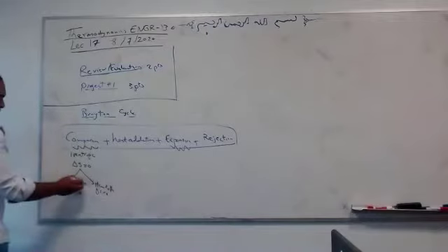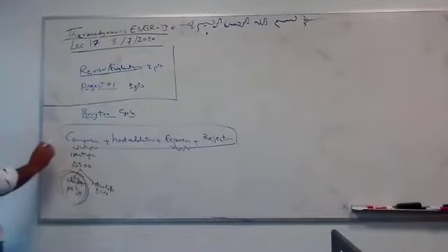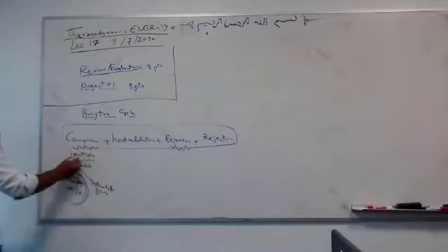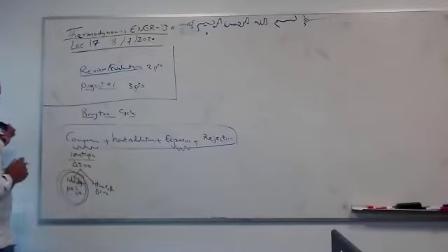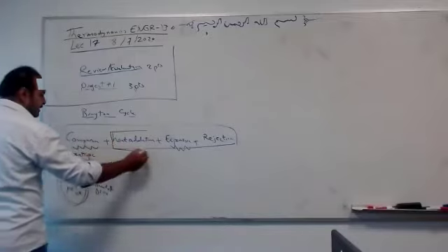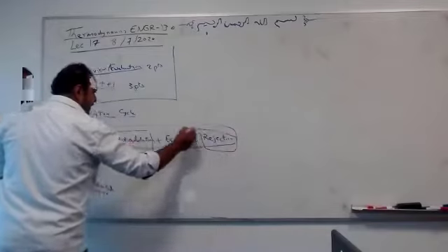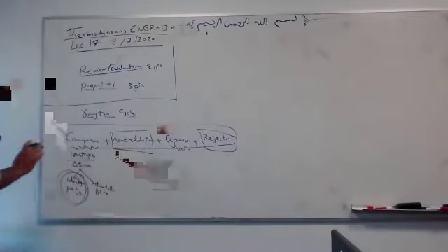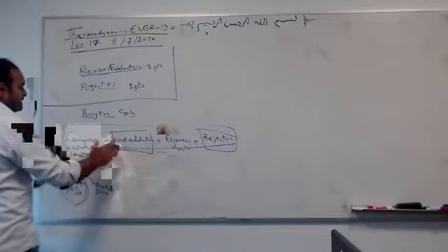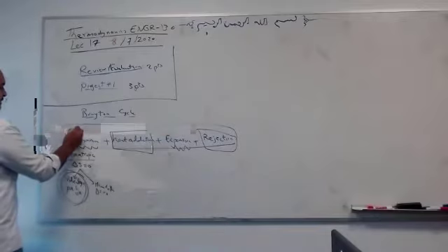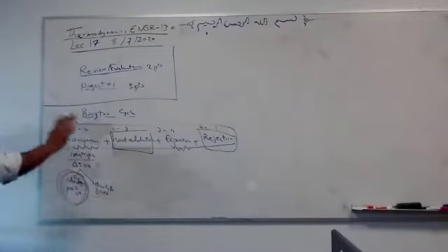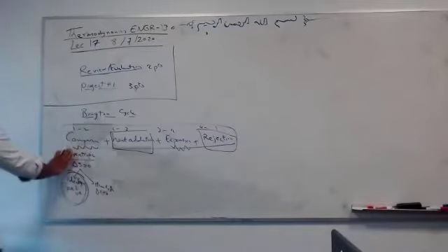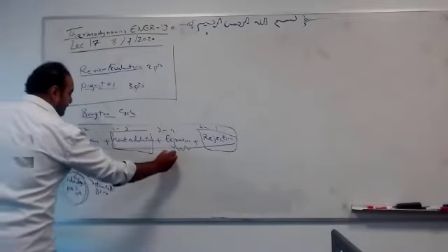So here all the cases were ideal gas. Compression and expansion are always isentropic: Otto, diesel, even Carnot cycle and some of the special cycles. The change was in heat addition and heat rejection. For Otto, both are constant volume, that's why we said Cv delta T, Cv delta T. So 1 to 2, 2 to 3, 3 to 4, 4 to 1, and go back. It's a cycle. The first process and the third process are always isentropic.